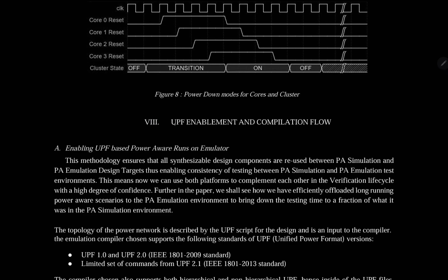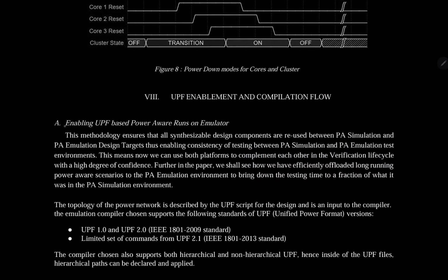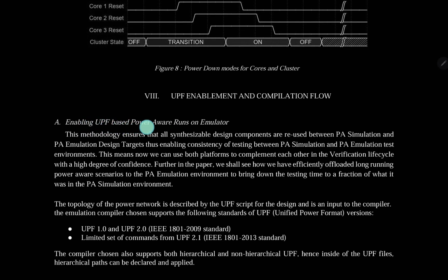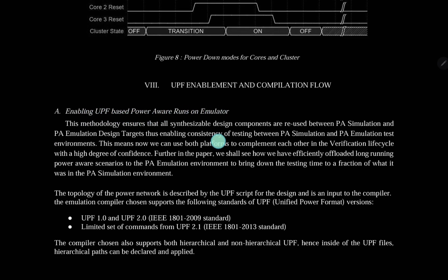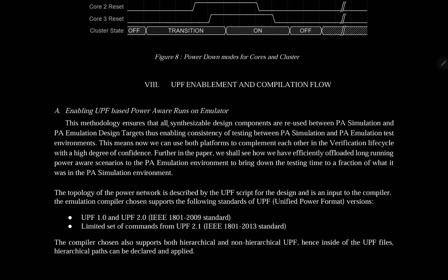So section 8 is UPF enablement and compilation flow. A. Enable UPF-based power-aware run on emulator. This methodology ensures that all synthesizable design components are reused between the PA-simulation and PA-emulation design targets, thus enabling consistency of the testing between PA-simulation and the PA-emulation test environment.